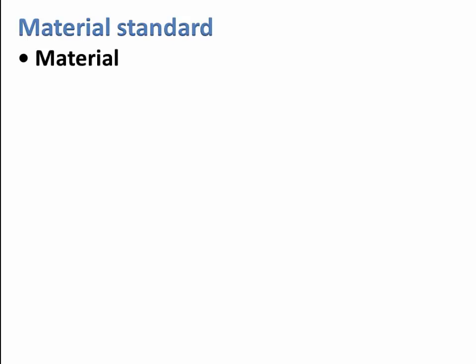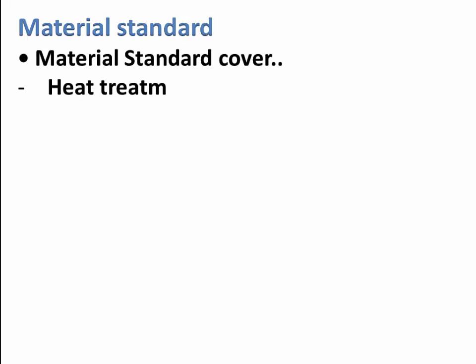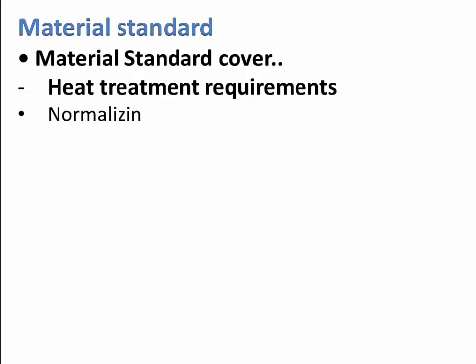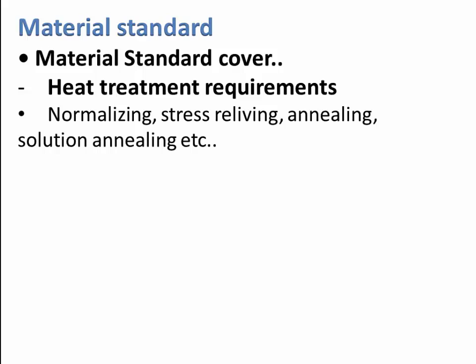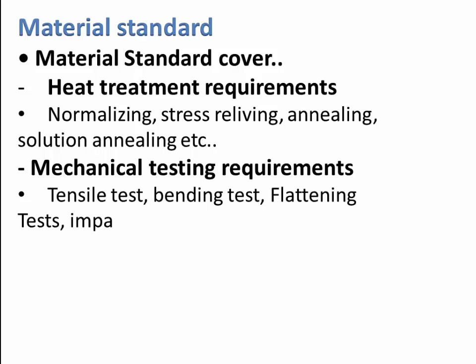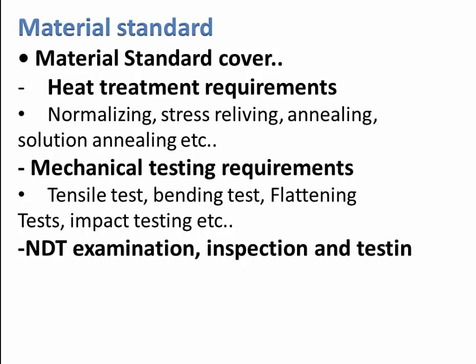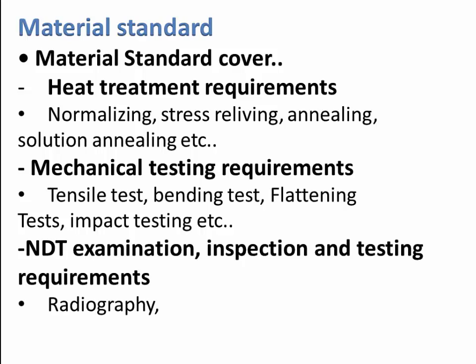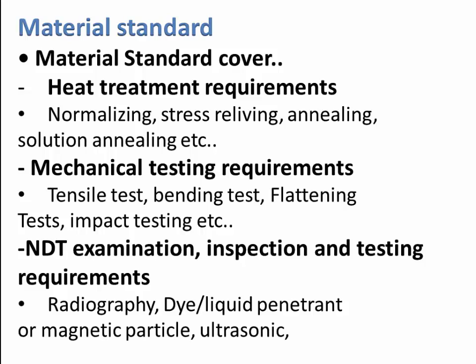Material standard cover. Heat treatment requirements: normalizing, stress relieving, annealing, solution annealing, etc. Mechanical testing requirements: tensile test, bending test, flattening tests, impact testing, etc. NDT examination, inspection and testing requirements: radiography, dye liquid penetrant or magnetic particle, ultrasonic, visual, etc.